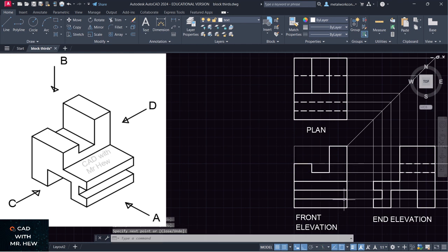All right. So if you're using a T-square and set square, just draw a T-square line coming over to the left from the highest point. Draw a set square line going up, and where these two lines intersect, you're going to draw a 45-degree line from there. Okay. All right, so let's go now.